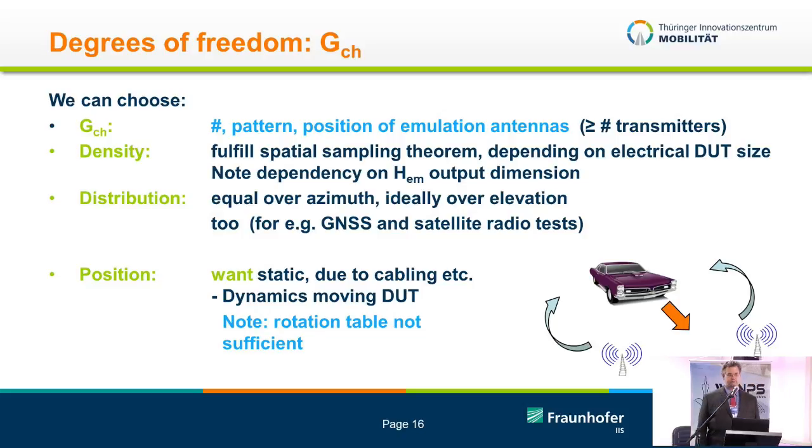You could think of, and that has been done for pre-faded simulation and for other ideas, that you just move the antennas during your tests if you want to change your system. This is something that should be avoided because you have all these cables, which is a general problem. Another idea is you can just move the device under test. Especially on a car, you typically have a turntable which you use when you do electromagnetic or antenna pattern measurements.